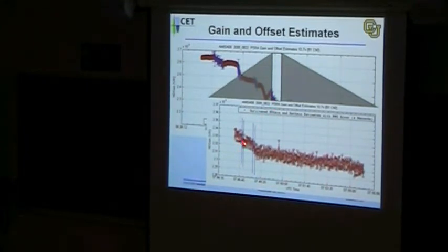You can see where we pin down the temperature of the noise diodes with the external calibrations, and then these are the gains associated with the noise diodes. But even these, quite frankly, are fairly noisy. And if you look at the 6 sigma variation here, that turns out to be on the order of 1% or so. Even that's too noisy. So how do we go and further determine what the real gain is?